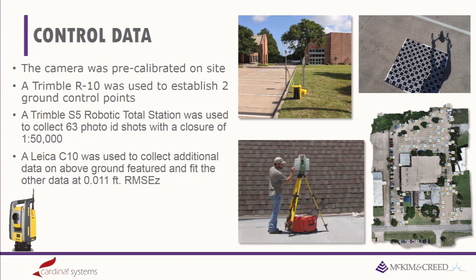So to do a good test, you need some good control data. So the first thing we did is on our site, we used a total station, and we collected 63 trig points. Our closure on that was 1/50,000, so very accurate closure.